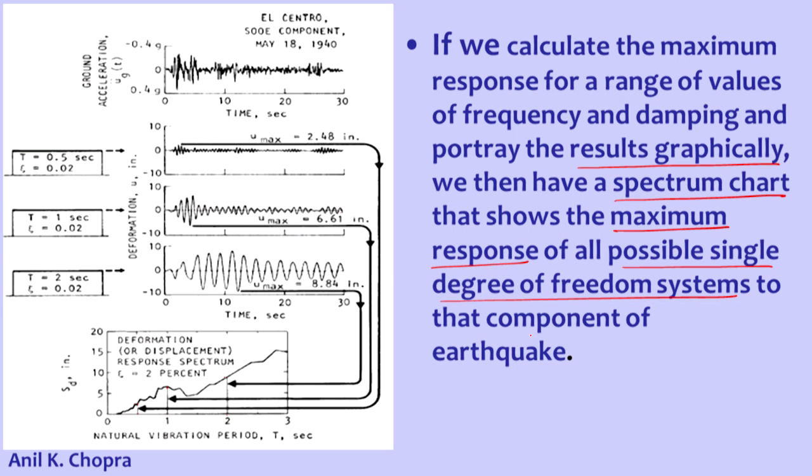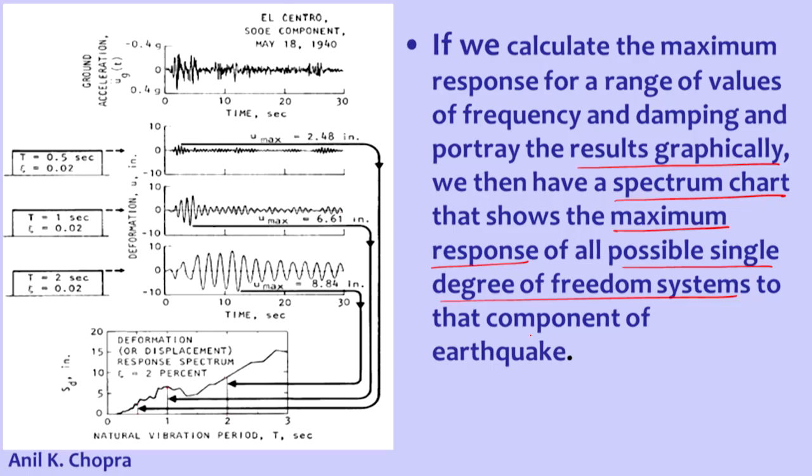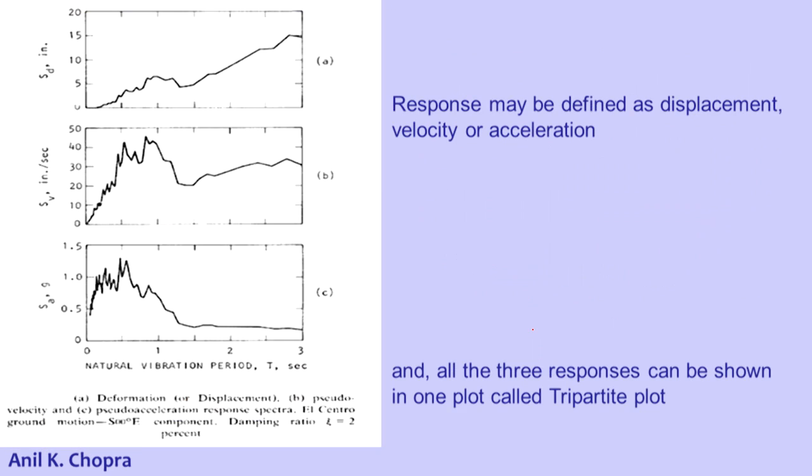That is the maximum displacement which that structure will undergo in the event of this earthquake or a similar earthquake, if they have the same frequency components in it. So this is the concept of response spectrum. It is an extremely useful concept in the application of earthquake engineering.